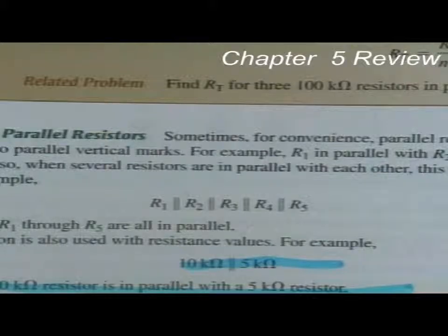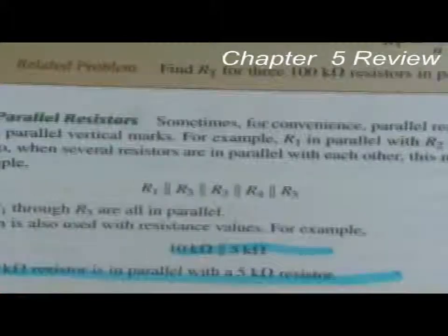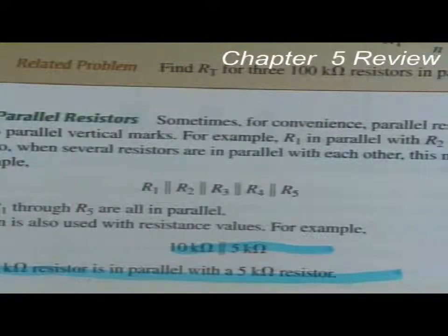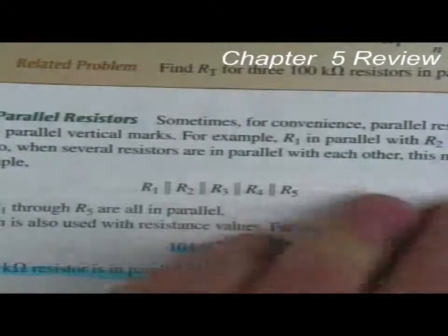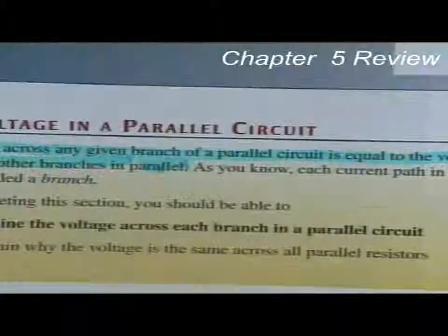Now, one advantage of a parallel circuit over a series circuit is that when one branch opens, the other branches are not affected. Let me give you an example. The old Christmas tree lights. Some of you are too young to remember them, but some of you are familiar with trying to find out which bulb is bad in a series circuit of Christmas lights. When one bulb goes bad in a series circuit, the entire circuit will open up.